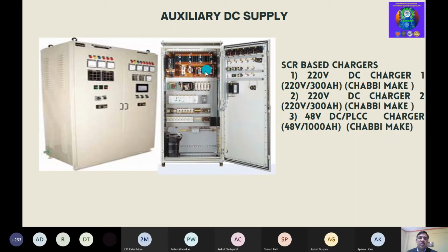So this is our actually silicon control rectifiers, that is thyristors, which are fitted on the heat sink. To absorb the heat from the thyristor, the heat sinks are provided. Then protection for this thyristor, that is fuses, are provided. Then this is a transformer which feeds the step down AC supply to the input of the charger. Then you have some indication, you have some feeders from this. So such arrangements are provided.